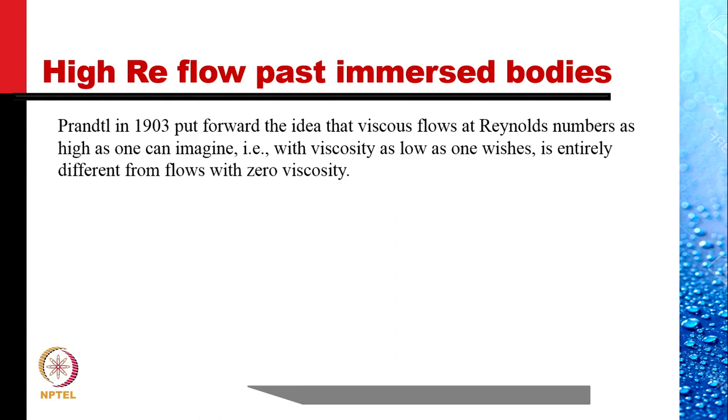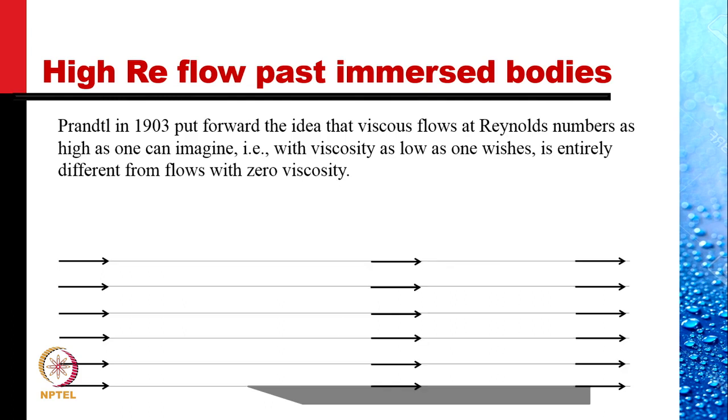If I have a flat plate and a flow parallel to this, if the viscosity is zero, we cannot satisfy the no-slip condition on the plate, and we have uniform flow throughout.